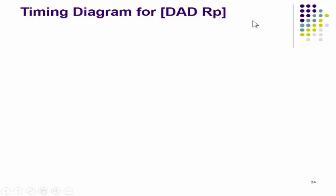Next interesting instruction is DAD RP. DAD is nothing but double addition, and you know its operation very well. This particular instruction adds the specified register pair with the HL register pair.